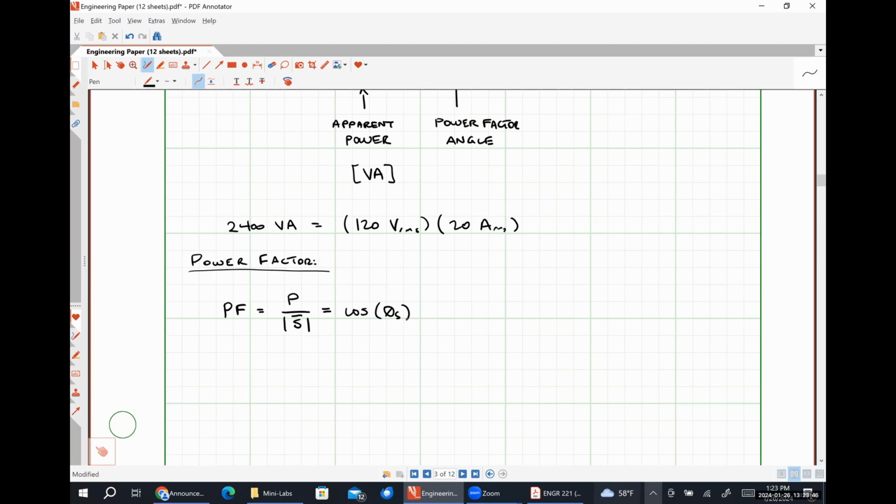And so at an installation where they have a large amount of reactive power draw, like a manufacturing plant, there are usually restrictions on how low your power factor is allowed to go before they fine you. And correcting that is all of what power factor correction or power factor compensation is: figuring out what can I put in my system to avoid paying a fine to the electric utility. We'll talk about that in detail on Monday.